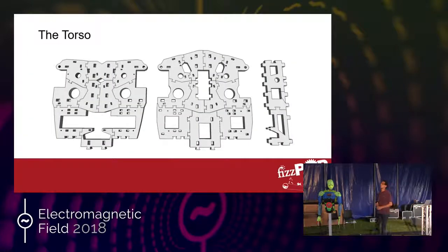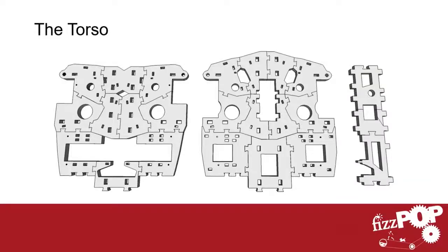The chest of the robot, because it's originally designed to be 3D printed, is made into so many different small pieces that you can 3D print and join together. The joints are not very robust. I found that out when the robot fell, and the same joints which are used in the shoulder all broke, so I ended up having to reinforce all the joints in the shoulder. But for the chest, from the start, I did not 3D print them because there are so many and they would take a long time to print. I would recommend just laser cutting them.